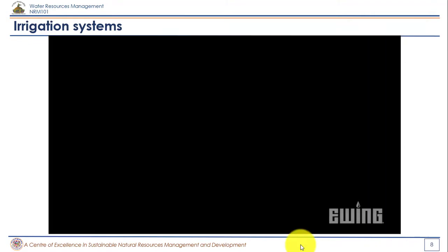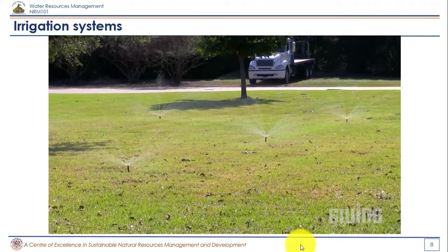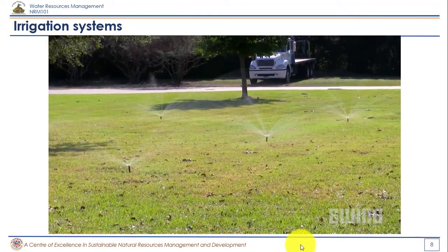The last bit of information we need is the available water at the source. In our example, we're going to have 18 gallons a minute. Now take the 208 total gallons a minute and divide it by the 18 gallons a minute of the source. And that will give us the total number of zones, which is 12. Now, that is our starting point. It's going to take a minimum of 12 zones to irrigate this. So yes, this is how we design irrigation systems.